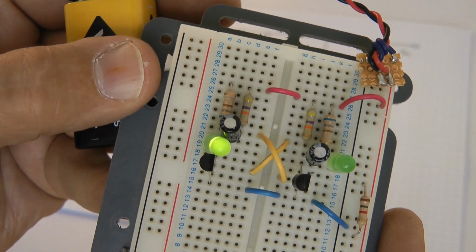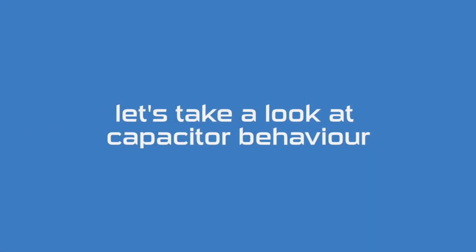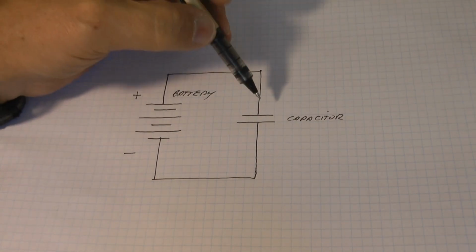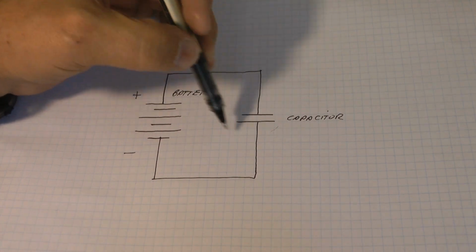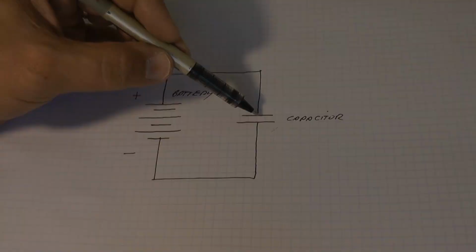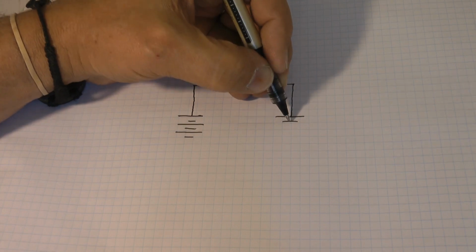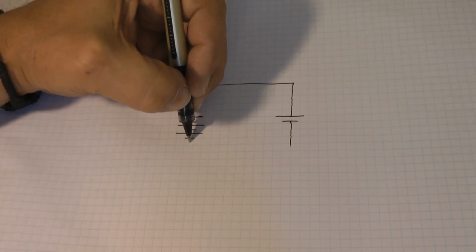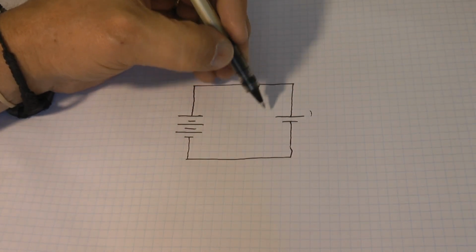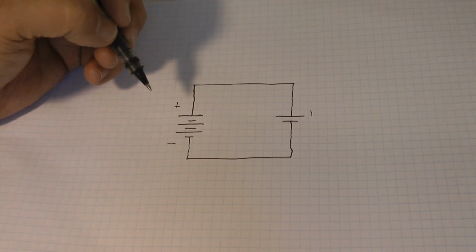That's the 2 transistor flasher circuit. The battery powers up and it charges up this capacitor, and just for a brief instant this capacitor looks like a dead short circuit. Once the capacitor has charged up, it starts to look like a battery. So we've drawn a symbol there looking like a battery. That becomes important later on in our explanation.